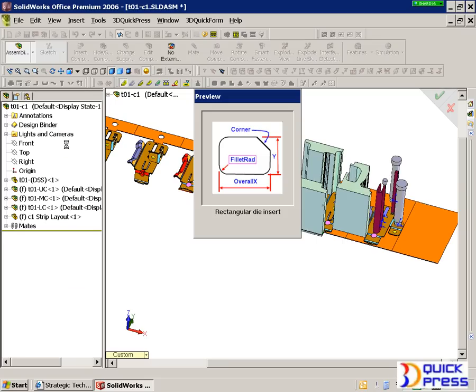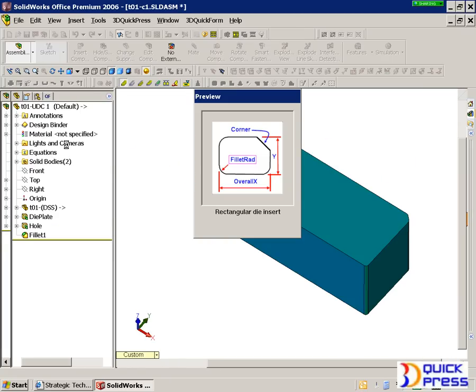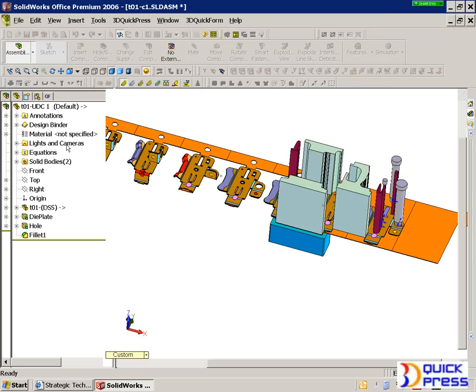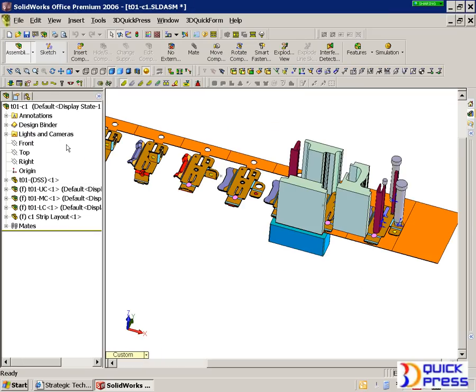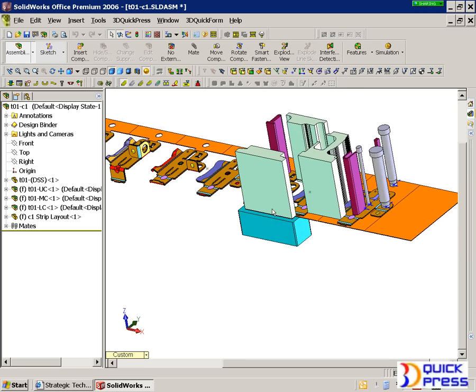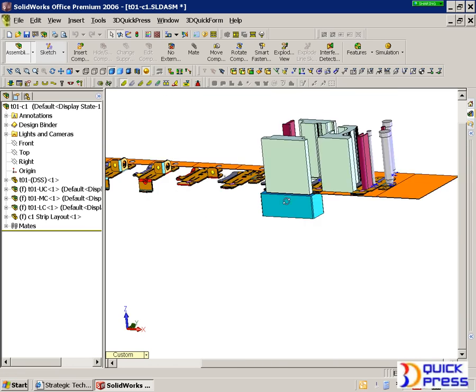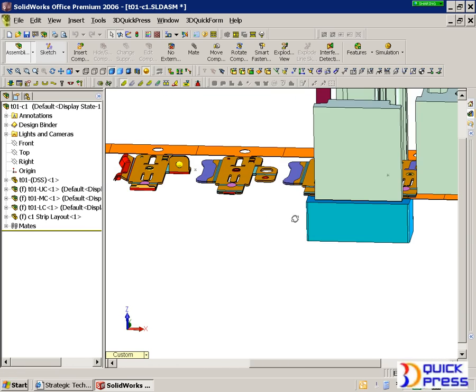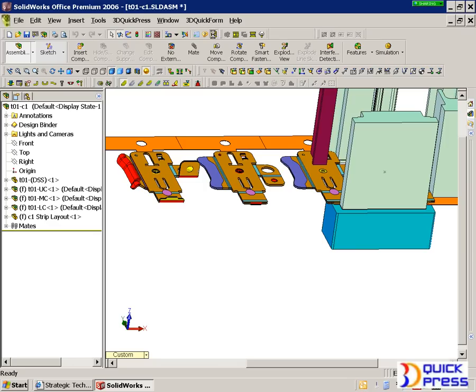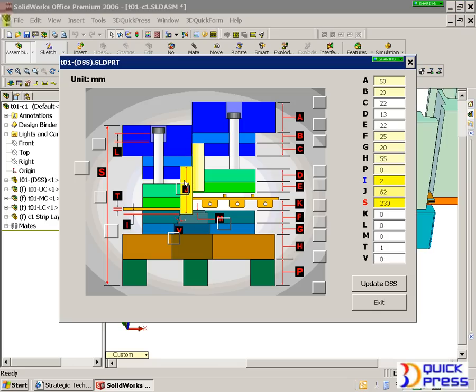The automatic adoption of this die insert will pick up on the current die plate thickness of the job. It will automatically find the center of that punch, and it will build it to my specification of 65 by 25. You'll also notice that it picked up on the thickness, which we haven't shown you the thickness wizard yet, but that's right here in the menus. And I purposely don't show it up front, because if I knew everything up front, it's real easy to design, right? And then it wouldn't be design, it'd be called robots. And you can see here that we can tweak anything about the job we want.